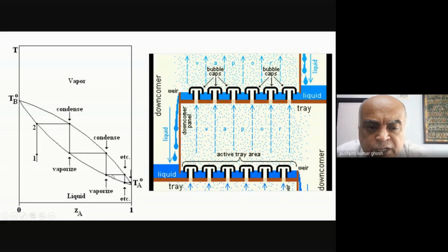When we talk about a theoretical plate in distillation, the more theoretical plates I have, the fractionation will be cleaner and cleaner, and I'll have pure liquid, maybe pure oxygen liquid, and I'll have pure nitrogen vapor. Is it clear to everyone?